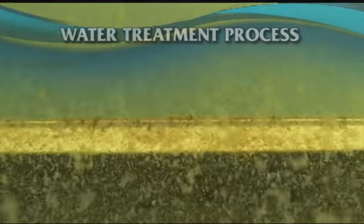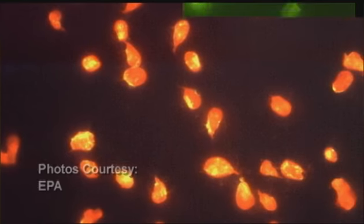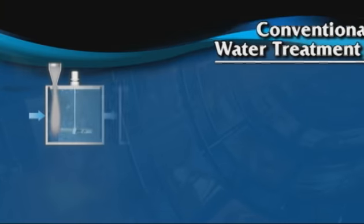One of the first and most important things drinking water operators must evaluate when raw water is pumped into the treatment plant is its turbidity, or a measurement of particles in the water. The particles make the water look cloudy, but they aren't just an aesthetic problem. Particles can also act as a shield for harmful pathogens, preventing them from being killed by disinfectants, such as chlorine. So, turbidity must be removed.